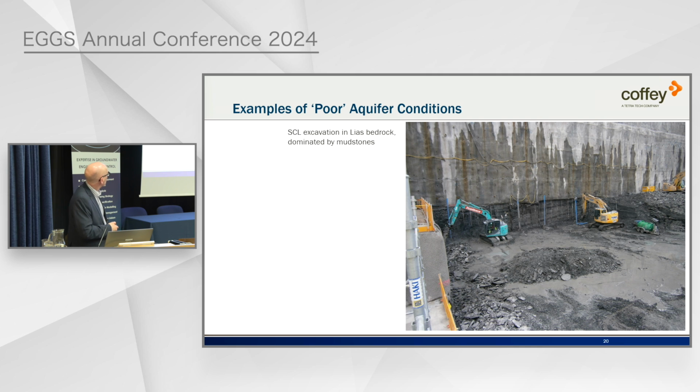This is a large rock face. It's vertical, soil nailed, and has a sprayed concrete lining on it as well. And here, there's some drainage, but you can just see here, again, that there are some gently dipping limestone beds. And here, the mudstone is generally really low permeability. You can see they've got surface water ponding on the excavation here because the vertical permeability is really low because of the mudstone, but it has a significant horizontal permeability contained in these localised beds.